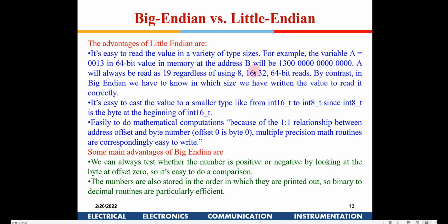In Little-Endian, it becomes easy, first of all, once the data is stored here, it starts from the LSB. So if you later realize that the MSBs are all zeros, in the read operation you can just pick up from the starting point of the address the required number of bytes.